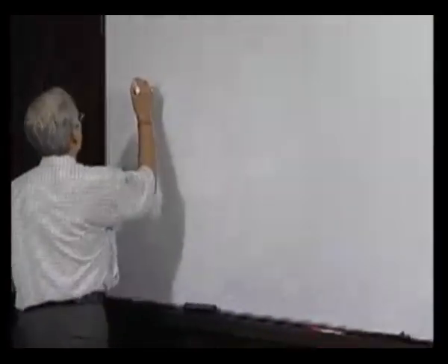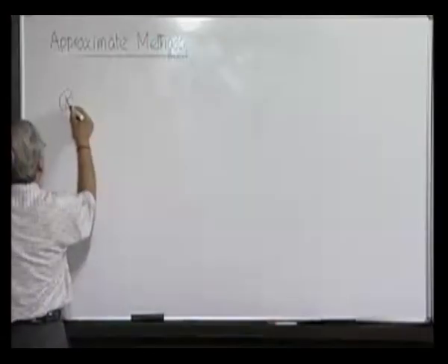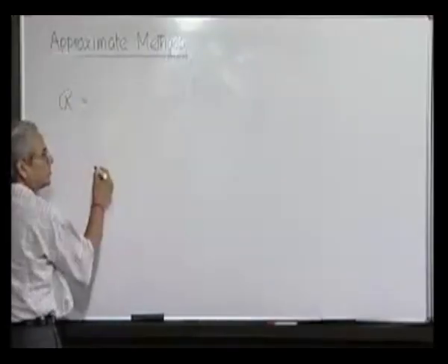However, when it is required to find out higher frequencies or higher mode frequencies, it is possible to devise a method of this approximate nature following the same principle and employing one of the important properties of Rayleigh's quotient. We have seen that Rayleigh's quotient is equal to